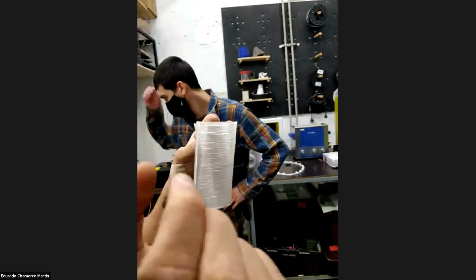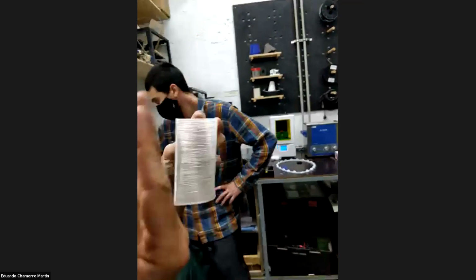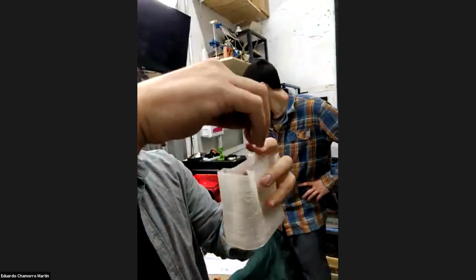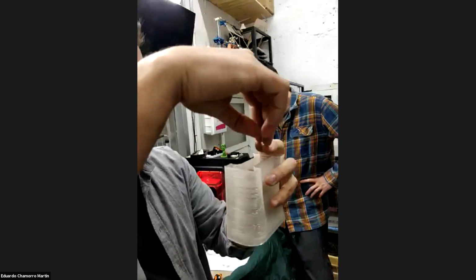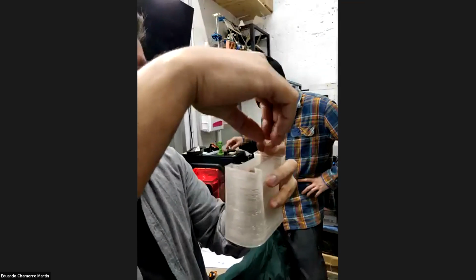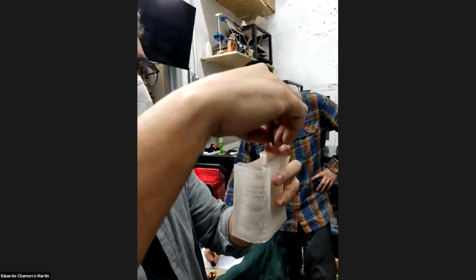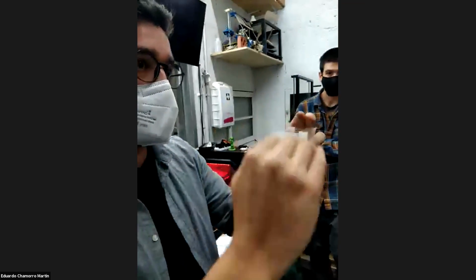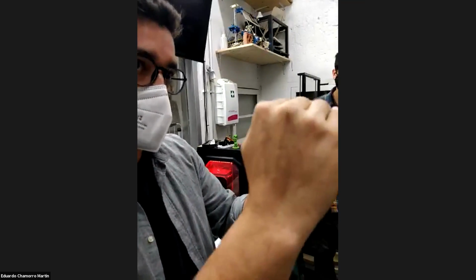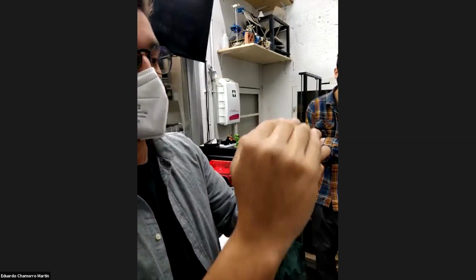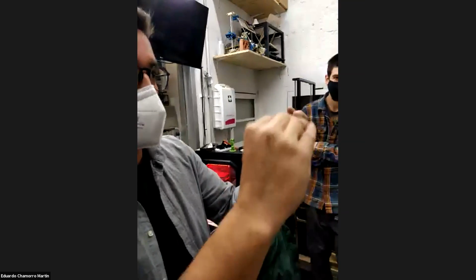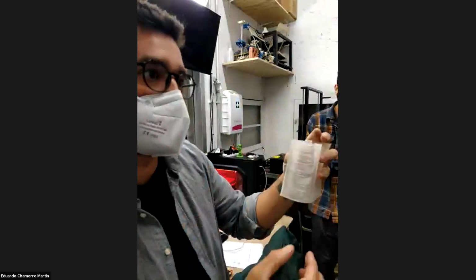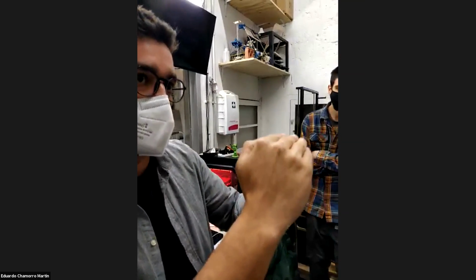The rotation of the screw is not exactly even in all the rotation, and the nut has a little bit of play. So if we are pushing more plastic and the plastic cannot get out, the Z is moving a little bit up. It's moving the whole bridge up because the plastic has more force, since we have a little bit of play. So that's the banding, caused by the vertical backlash of the Z that we have in the 3D printer. To avoid that, first calibrate the printer, and second, put an anti-backlash nut on the Z, or try to replace your threaded rod because it might be too used and have more tolerance.